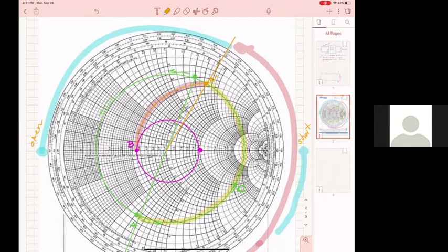Can I clarify one thing? Yes. So just trying to get general intuition of the Smith chart here. At this stage, we're flipped to the admittance version of our Smith chart. Yes. Right. And in this case, when you follow the constant resistance line counterclockwise, you're adding, sorry, I'm losing my train of thought, but that's adding a negative reactance. So that's adding a capacitive shift.